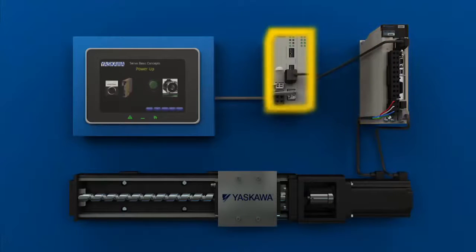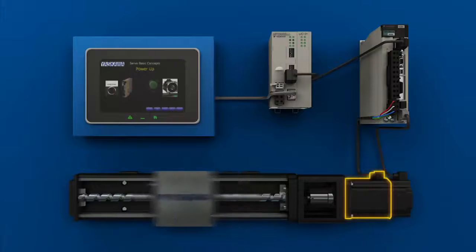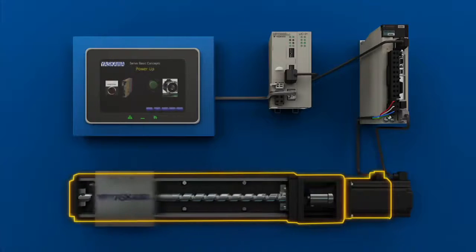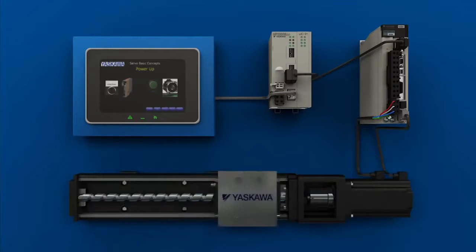Connected to the controller, you'll find an operator interface. The interface is used to start, stop, and adjust the various functions of the machine. Interfaces can be simple buttons and indicator lamps, or they may be a more complex human-machine interface, or HMI. On the other end of the process, the servo motor is connected to a mechanical system that it moves, the servo mechanism. This is a common example, a simple linear actuator that translates the servo motor's rotary motion into linear motion, in this example using a screw.